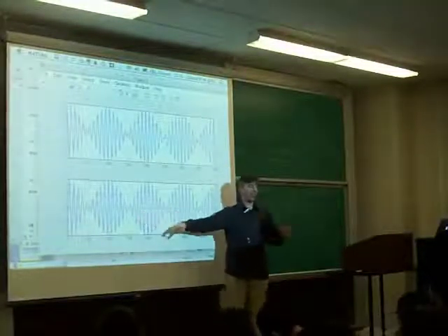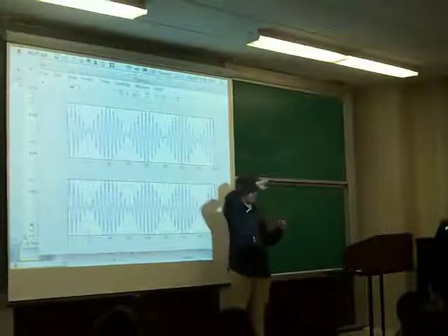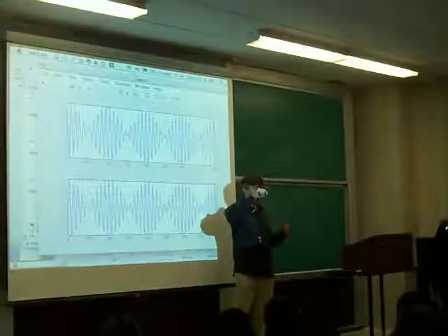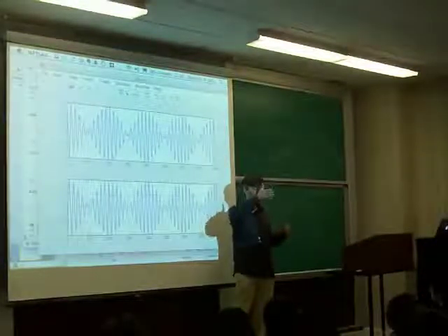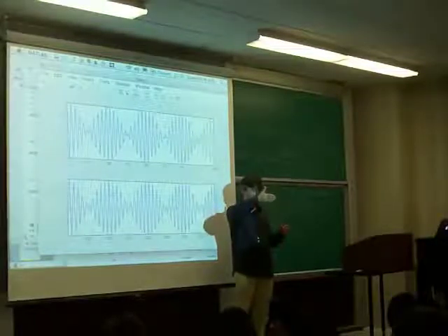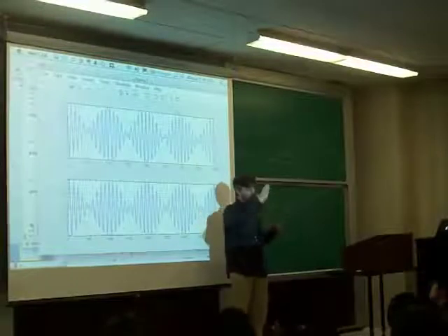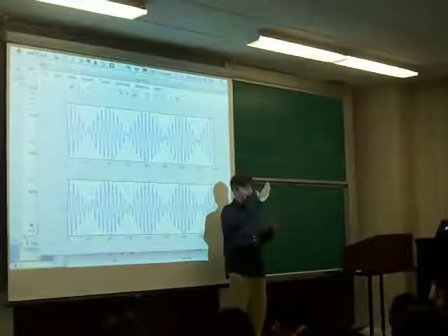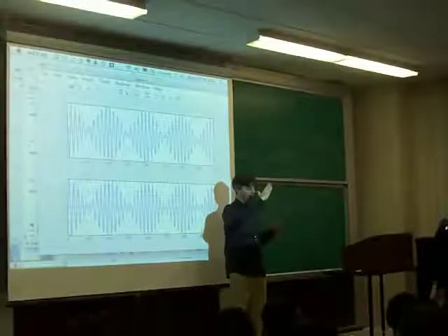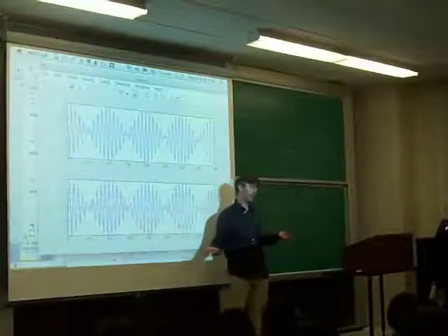If we analyze this system which has a phase response, then we can characterize its behavior near a center frequency, what the actual phase shift of the carrier frequency is, which is going to give us the phase delay, the time offset of the blue lines. And then we can also characterize it as a slope, the first order fit of the phase response in that region, which is going to give us the group delay, the shift of the red curve. And those two things are separate.